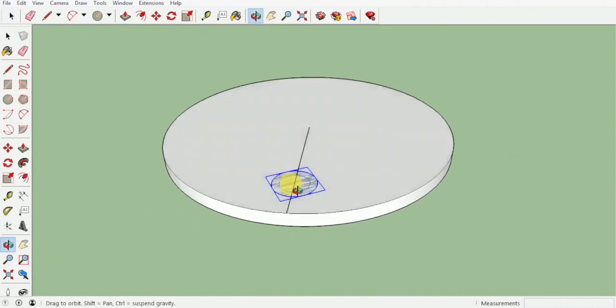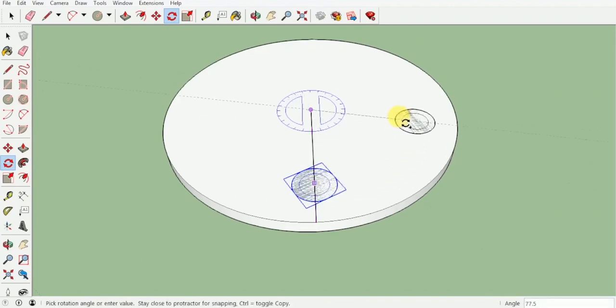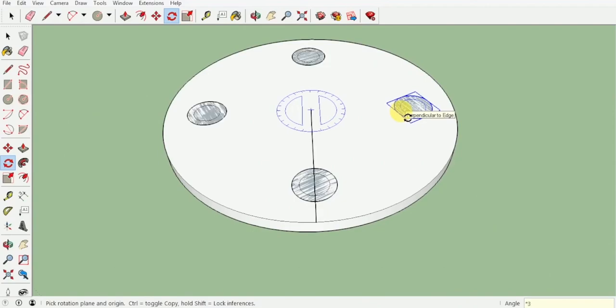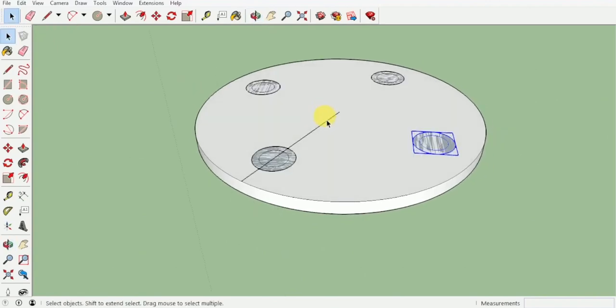Now once I'm done with this, the next thing I'm going to do is select the rotate command and I'll make sure I'm setting the center of the circle as the axis, and I will select this circle by pressing Ctrl. I will copy this circle 90 degrees and then I will just do *3, enter. So it copies it and arrays it along this entire curve. So you'll now be seeing how we're amalgamating all the movements, all the uses to actually create what we want.